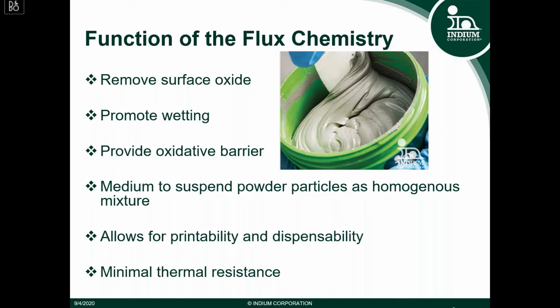It also, as I mentioned previously, has the consistency of honey. So you can use it as a medium to suspend the solder powder particles and make it a homogeneous, smooth mixture, easily for processing. You want to make it easy for printability and easy for dispensability. You want to make sure that the solder bead on your stencil is rolling smoothly and is dispensing smoothly. And then one final comment about the flux chemistry, you don't want it to interrupt the thermal transfer efficiency. So it has to have minimal thermal resistance.